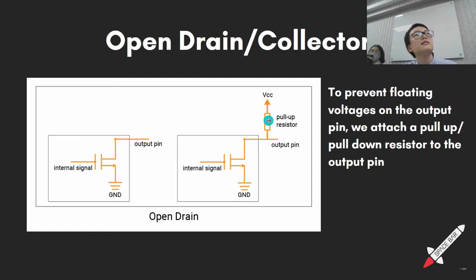Okay, yes. So basically, when the switch is turned off, the output pin is not connected to ground, and it's not connected to high. So what is it? Don't know, right? When we don't know what this voltage is, we say that it is floating. Floating basically means I have no idea what this is, and this means there's an undefined behavior on my GPIO pin, and I don't know what my microcontroller is doing now.